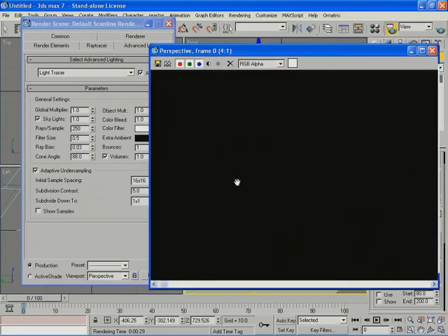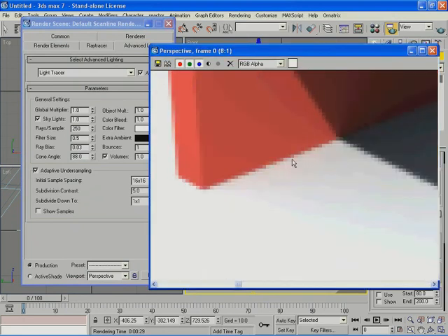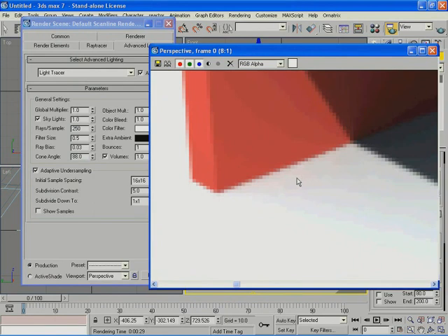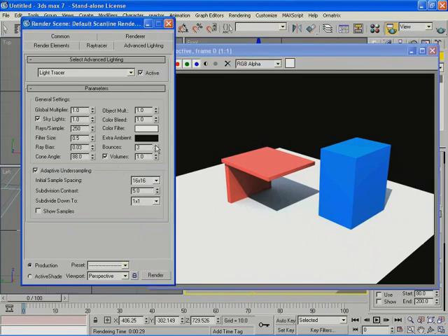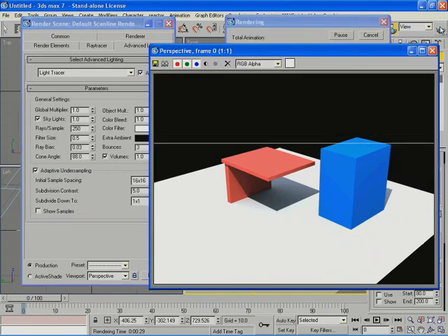Now, the more bounces I have, the more reddish this area is going to be. So let's set this to 3. And because of the light bouncing inside, I'm going to get a brighter area inside the occlusion. So now with 3 bounces, I get a much more realistic sunlight rendering, and I would start to see the color bleed, which is the reddish tint down here. So now it's very visible. Now in this area, it's not so visible because of the bright area coming from the sunlight.